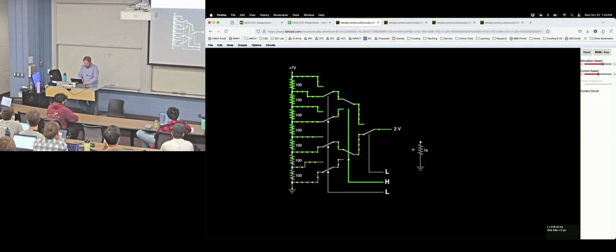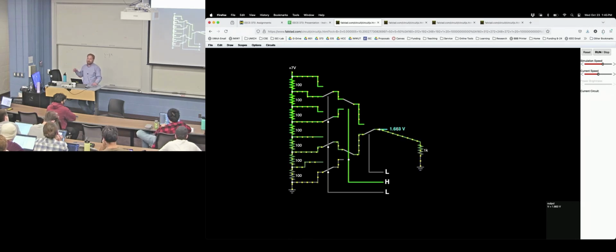So that's wire. If I connect this, it's dropped that down. Right now it's drooping because this whole path is now the source resistance. So whatever that is, 500 ohms of source resistance divided by the relatively high impedance of a kilo ohm, right? This voltage divider has dropped that voltage down. It did want to be 2. That was the desired output voltage, but it couldn't make it. So now we should put that buffer in here to overcome that issue.